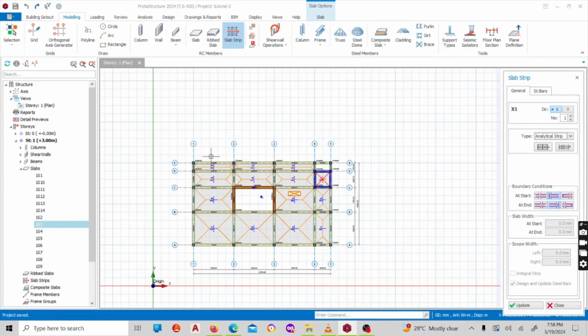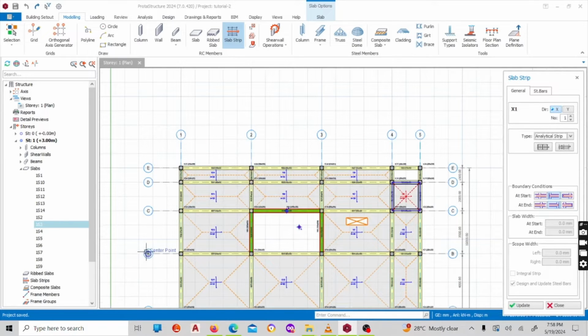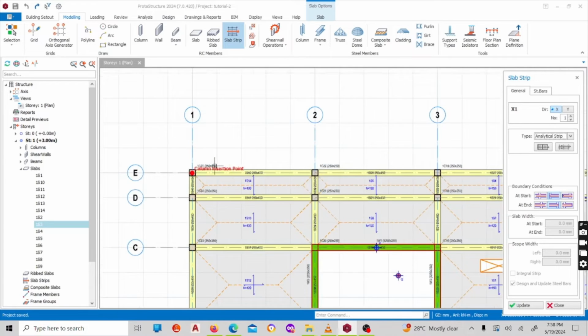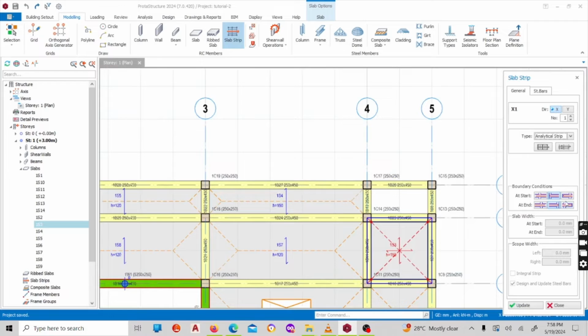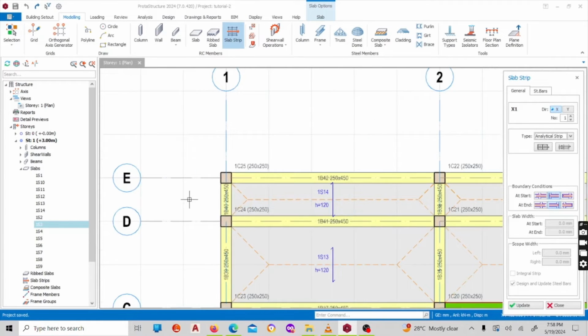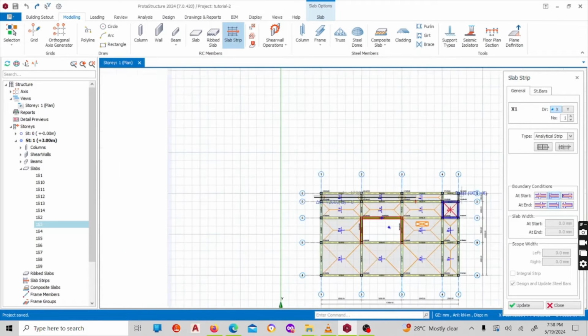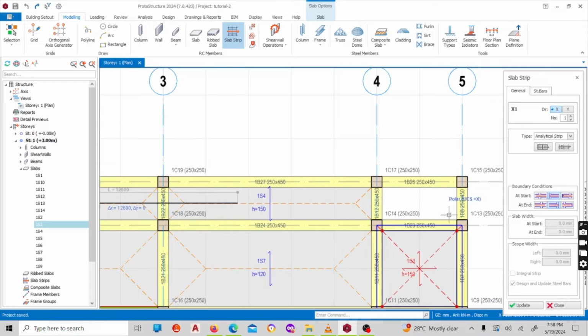So coming back to here, we want to put along the x-axis, this direction, going to the right. Look here, the starting point is a beam, the end part is a beam. So I have to choose this and this. I just come here, left click, hold control to make your rebar straight, and left click again.